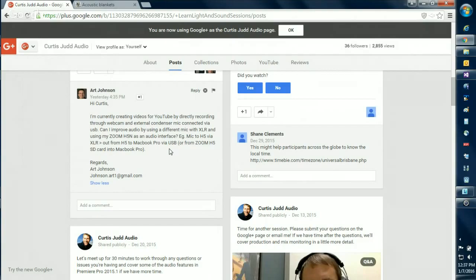So in that case, you're relying on both the preamplifier and the analog to digital converter that's built into the microphone. And to be honest, that microphone cost me, I think, $50 US. So it's a relatively affordable microphone. So when Audio-Technica made that microphone, they had to skimp somewhere. And my impression is where they skimped was on that preamplifier potentially, and possibly also its analog to digital converter.